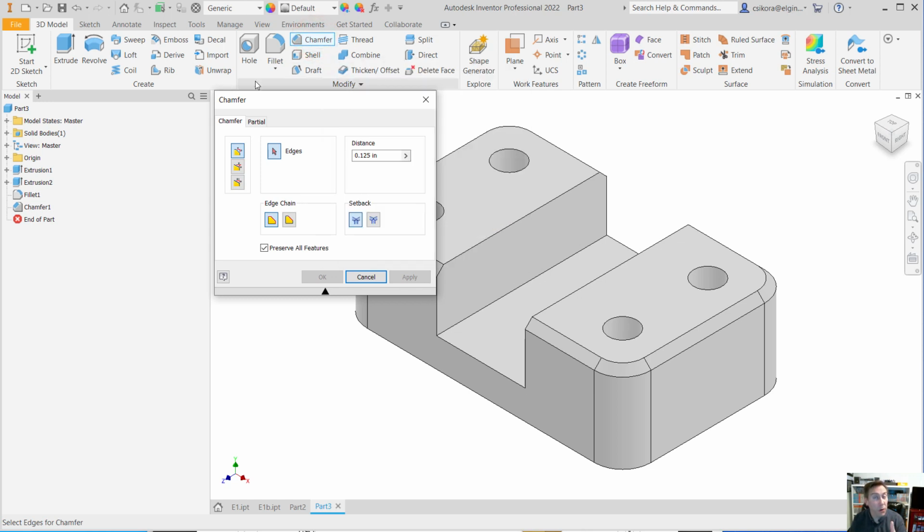Note you can use the chamfer for a countersink too. In the Hole tool, though, it has the standard countersink, so you might want to wait or just go to exercise 4, and near the end I go through how to use it, and that has the same, a little different, but anyway, let's set it to 0.25 and select the edge, and you can see now we have countersinks in there.